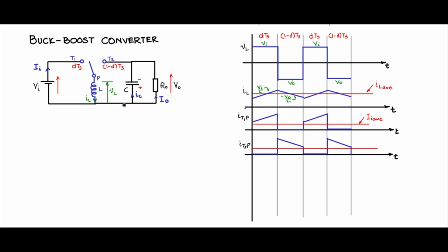Now this current, the same current flowing here also, splits in two parts, IC and I0. IC is the zero average part and the average part flows through the load. So the average part is nothing but I0. Looking at the figure, you can see that the average part has to be I0 and the non-average part flows through IC. So in effect, if I remove this average part, bring down this waveform to zero average, I will get the current through C, that is IC. If I do that exercise, I will be bringing down the waveform by I0, removing the average part. So this amount which it has come down is equal to I0. Now this waveform will have zero average because the current through the capacitance has to be zero average under steady state conditions.